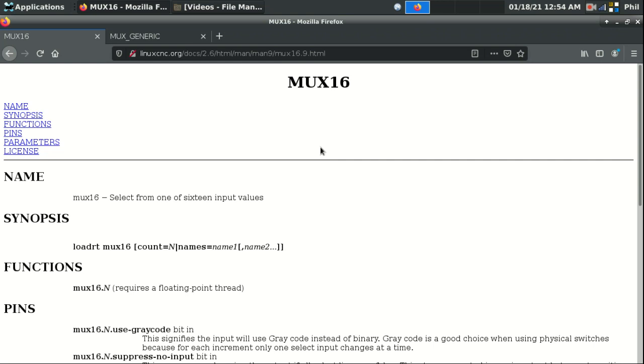And with that, if I wanted to use a feed override knob, I would use probably a mux8 or a mux16 and then have that many positions available for my rapid or my feed override. In my case, I'm going to be using potentiometers, so I'm using the analog input settings on my Mesa card to eliminate having to use multiplex switches or have that many inputs going to a single switch one-to-one to each position.